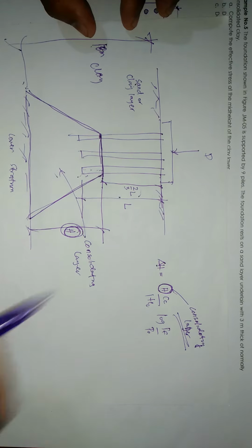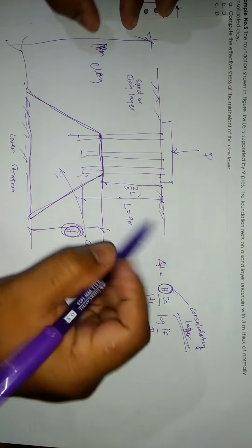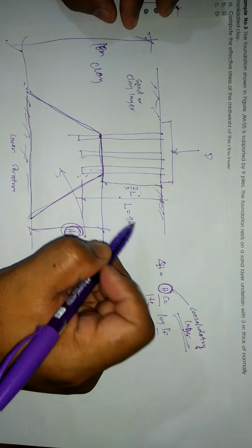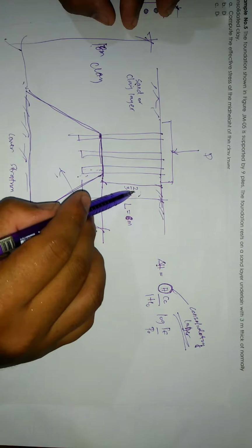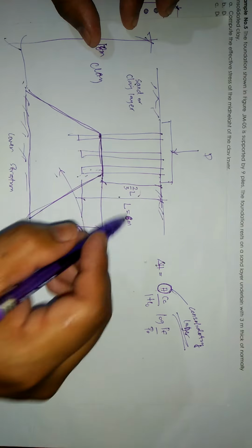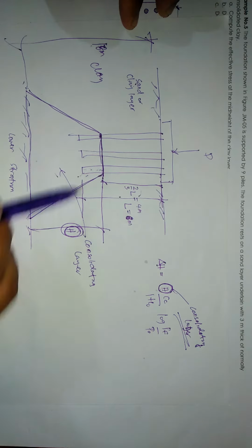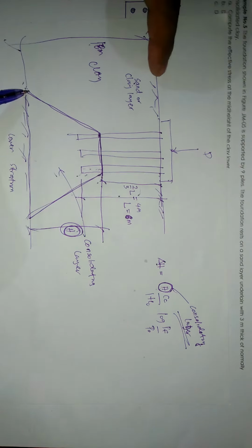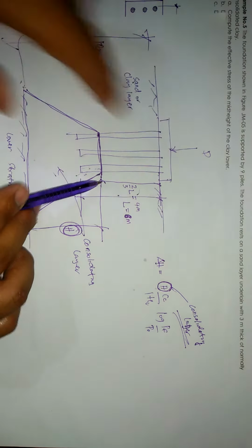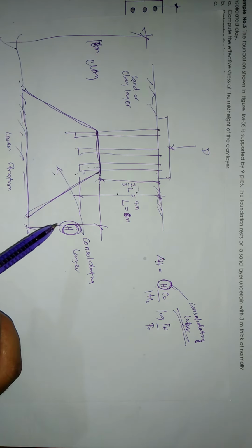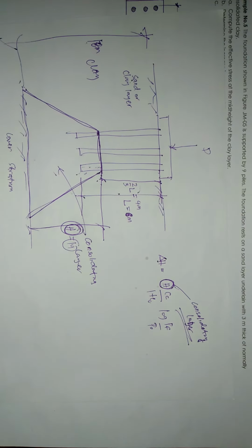Okay? So, for example, if the length of pile is equal to, let's say, 6 meters, 2/3 of it is 6 times 2, 12 divided by 3, which is 4. So 2/3 of L is 4 meters. Tama? 4 meters yan. If the layer is 18 meters and this is 4 meters, 18 minus 4 would be equal to 14. So, your consolidating layer would be 14 meters.